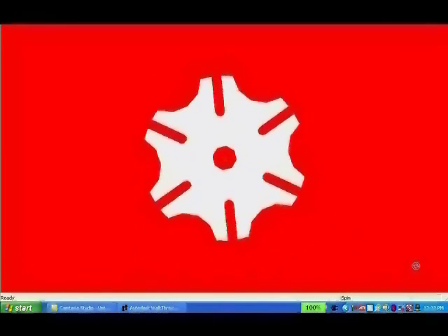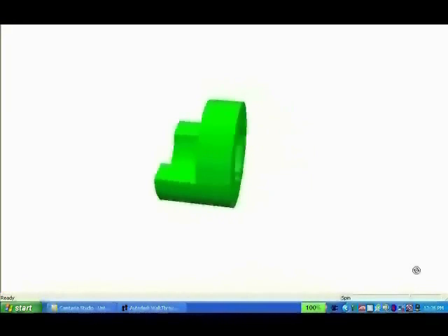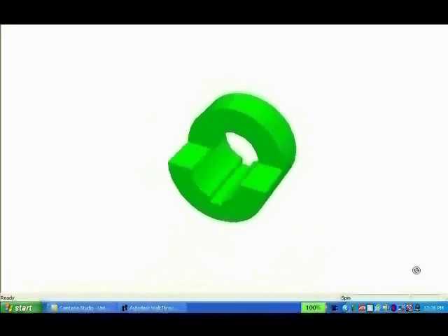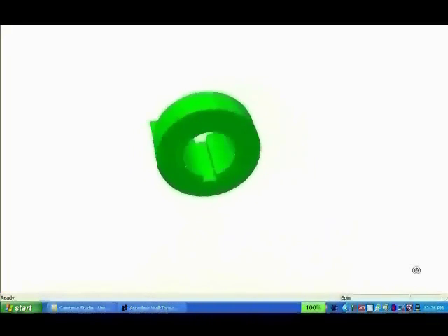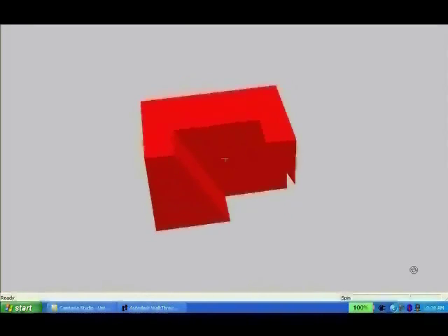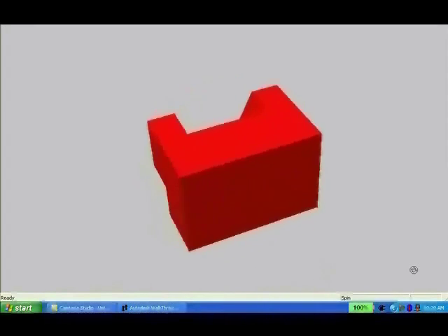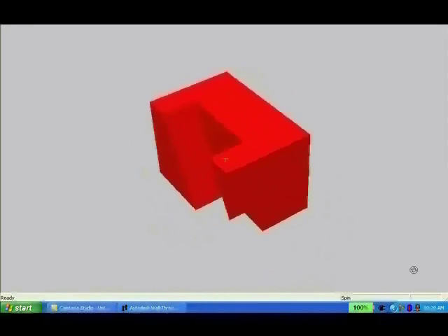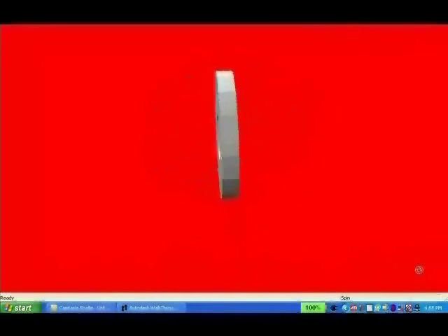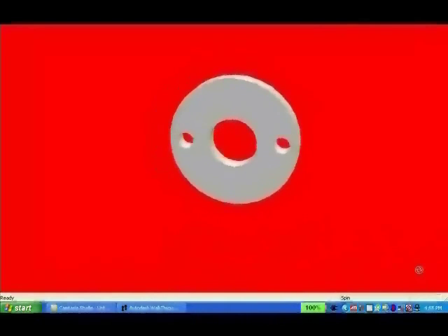Scale factor too is very important. You might want to draw a football field and need a scale of 1 to 100, or a map and need a scale of 1 to 500. You might draw something like a laptop or a piece of furniture, and your scale might be 1 to 1 or 1/4. You might want to specify on a drawing different units such as decimal, fractional, or architectural units. Hopefully by the end of my course, the freshman students have learned all that and more.